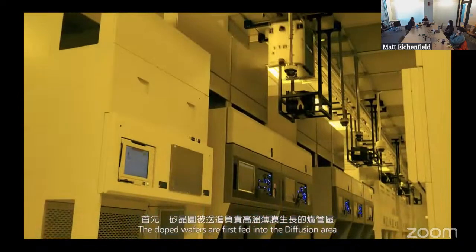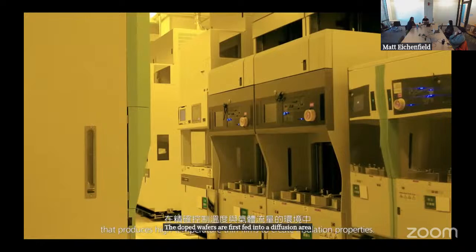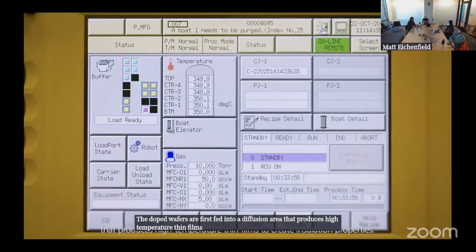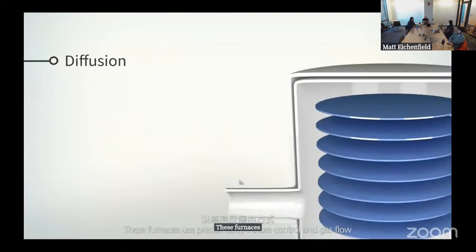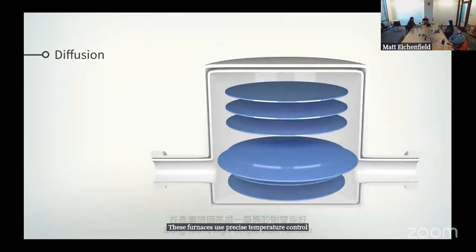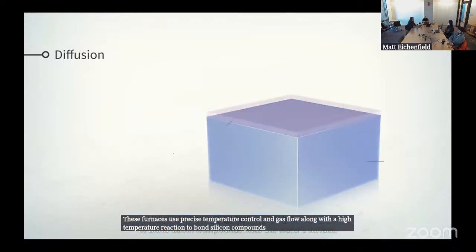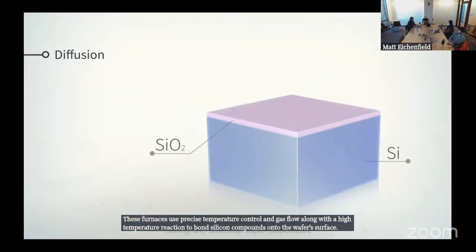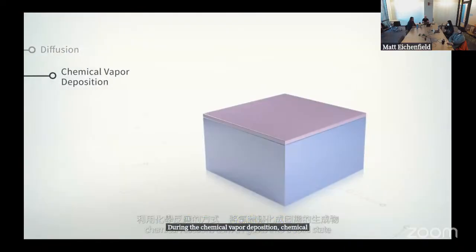The doped wafers are first fed into a diffusion area that produces high-temperature thin films to create insulation properties. These furnaces use precise temperature control and gas flow, along with a high-temperature reaction to bond silicon compounds onto the wafer's surface. During the chemical vapor deposition, chemical reactions convert gases into a solid state to form the thin film.